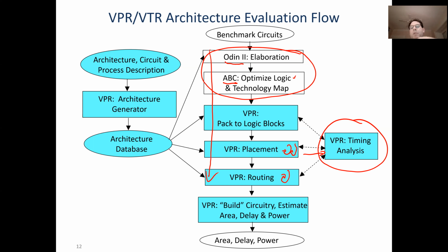Or you can input all of the timing parameters because you've done your own transistor level design, and it'll add everything up and tell you what the area, the delay, and the power are. The area is estimated basically the same way that we did last class. The delay is typically a bit more accurate because you input more detailed models based on SPICE and so on.